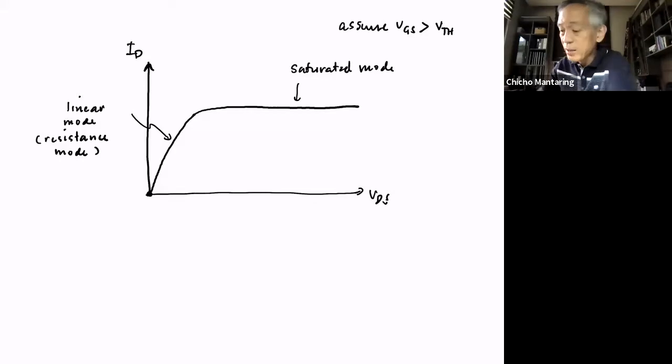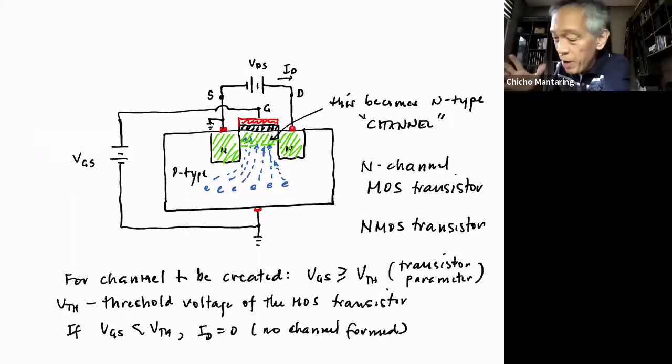Now you might ask, why does saturation occur? I don't want to go into the semiconductor physics of that, but maybe a very, very short explanation. The reason why saturation occurs is because VDS has an effect on the electric field. I said that these electrons are attracted toward the gate or toward underneath the oxide because of the electric field that is set up by VGS.